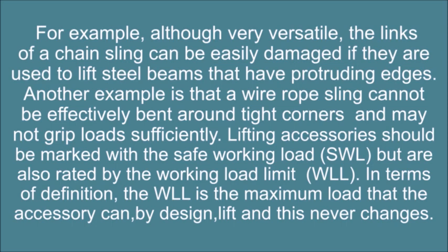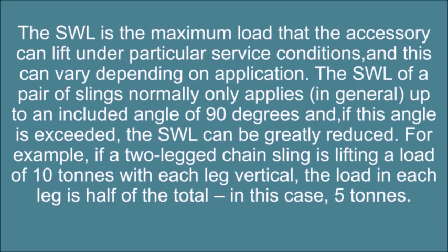Lifting accessories should be marked with the Safe Working Load, SWL, but are also rated by the Working Load Limit, WLL. In terms of definition, the WLL is the maximum load that the accessory can by design lift, and this never changes. The SWL is the maximum load that the accessory can lift under particular service conditions, and this can vary depending on application.